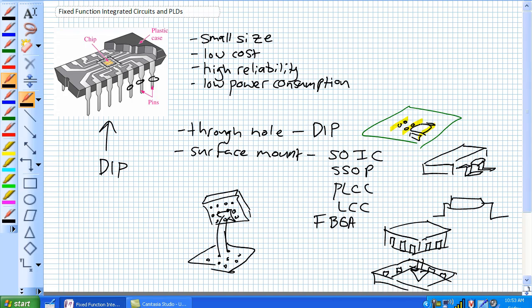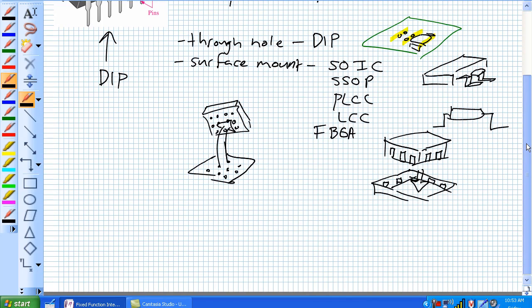Okay, so we are going to be using TTL through-hole DIP. And we need to come up with a scheme to identify these pins, because there's a number of pins radiating off of it. And long story short, take your chip, find the identifier.